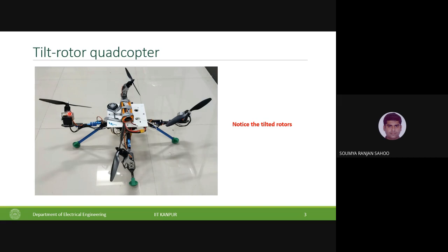In such a case, I would have my thrust vectors aligned in such a way that my quad maintains a zero attitude. When I say zero attitude, it will neither roll nor pitch while moving in the horizontal direction. So in this design, I can move in the horizontal direction without having a roll in the quad rotor. That is why I can scan the horizontal structure. Similarly, let's say you are flying above and you want to scan something right at the bottom.